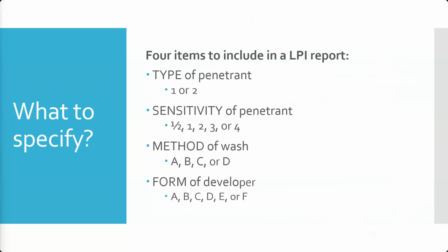Okay, how about methods of wash? A, B, C, and D. What's method A? Water. What's method C? Solvent removal. Who wants to take method B and D? Anyone want to? They're post-emulsifiable. And does anyone remember what B is versus D? Lipophilic, is that B or D? That's B. And what's D? Hydrophilic. So post-emulsifiable lipophilic is B.